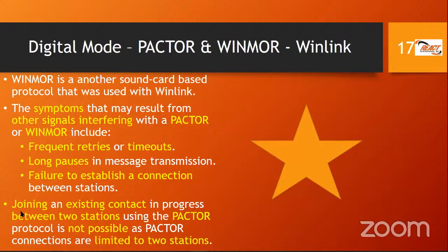The other thing that we need to know about Pactor is that if two stations are communicating using the Pactor digital mode, it's a station-to-station contact, so that you as a third person wanting to get into the conversation cannot. So Pactor is a station-to-station communication, and you have to wait until those two stations have finished their communication before you can have a communication.